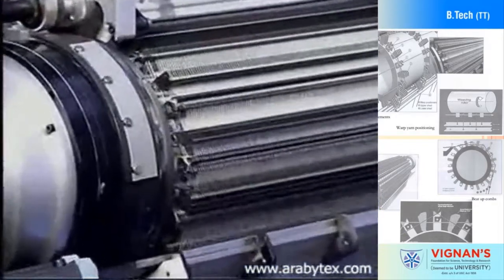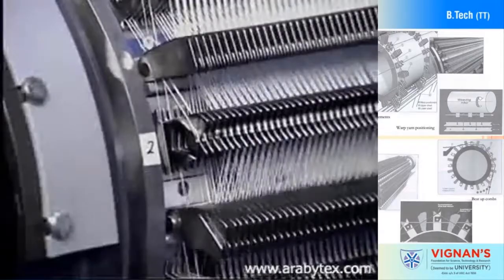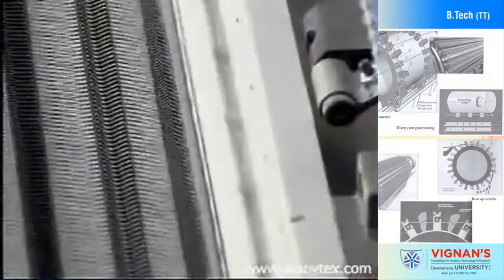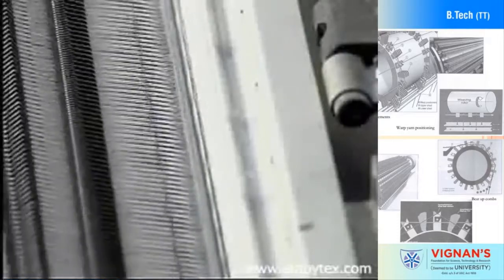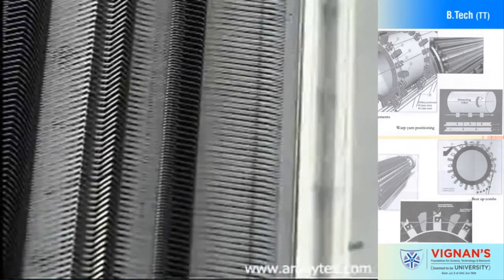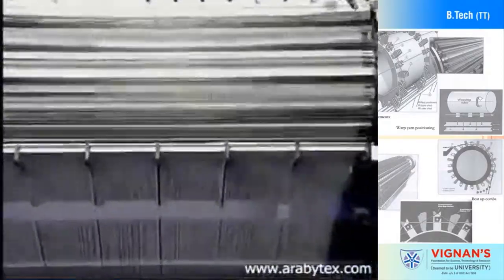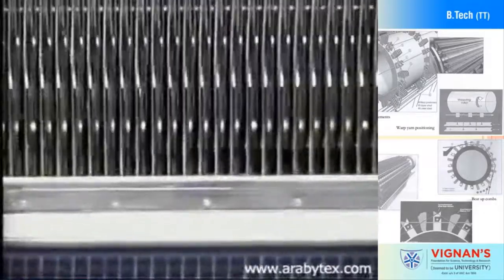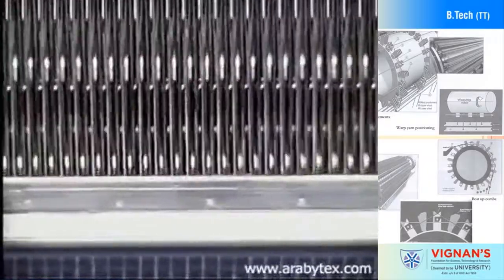As the rotor turns, the shedding elements keep the shed open for insertion. At the end of insertion, the shed is closed by the movement of the shedding element away from the warp ends. The closing shed removes the inserted weft from the weft channel for beat up by the reed. For example, to form the proper shed for a 1x1 plain weave fabric, the warp positioners move alternating warp ends above and to the side of the shedding elements.